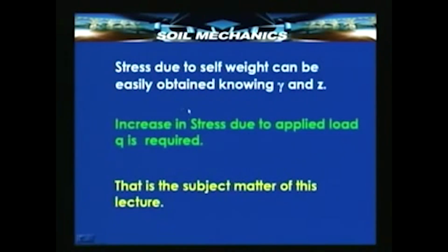Further, as I said, one component of the stress is the self weight, but then it can always be easily computed if we want, by knowing gamma and the depth z, because we have just seen that the vertical stress due to the weight is gamma z. So, it is only the increase in stress due to the applied load which we are interested in, and that is what we are going to discuss in today's lecture.